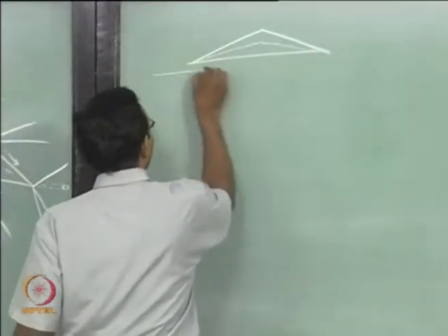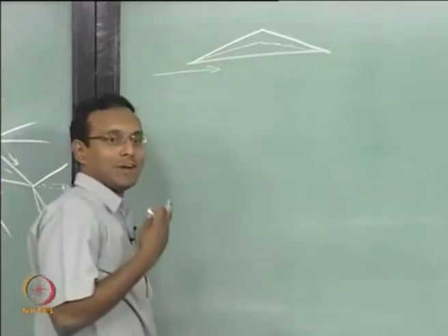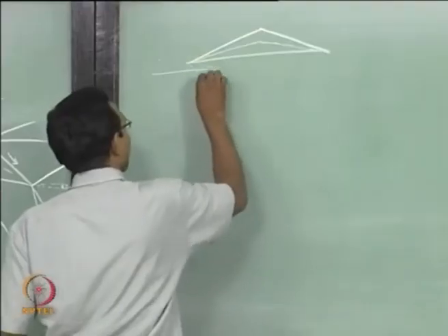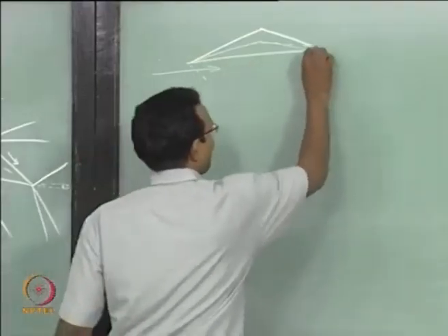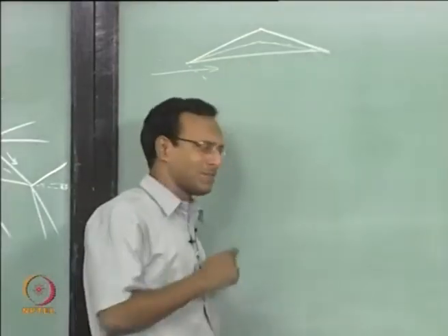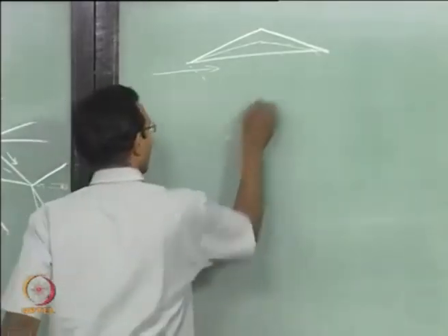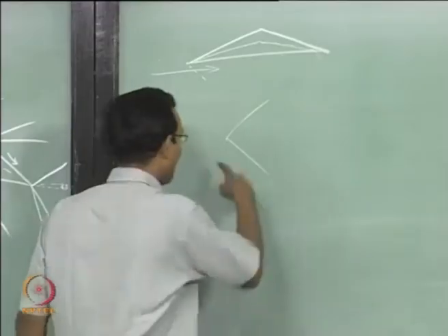I am going to say the flow here just goes straight. I am having 0 angle of attack. It just goes straight. If at all there is any wave, it will be a Mach wave, and that will be everywhere. Remember that Mach waves do not happen only at corners, they happen from every point in the flow. Even from somewhere here, there is a Mach wave going this way and this way. We are ignoring these Mach waves.